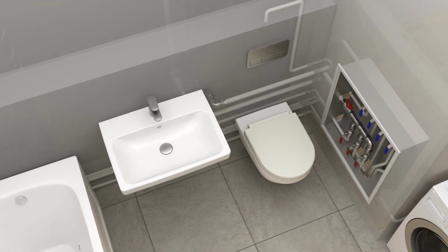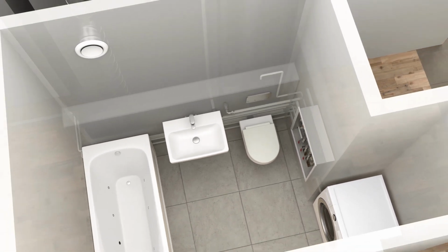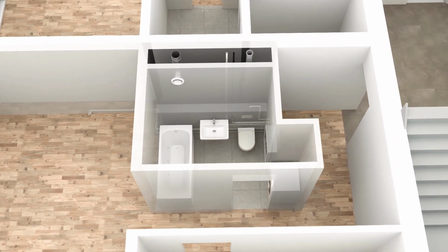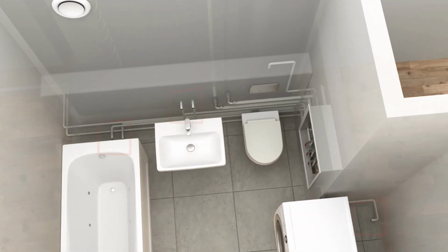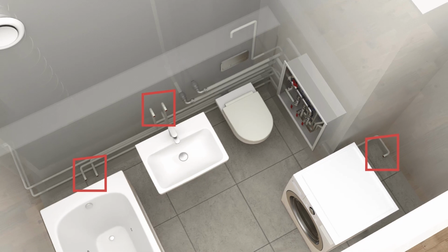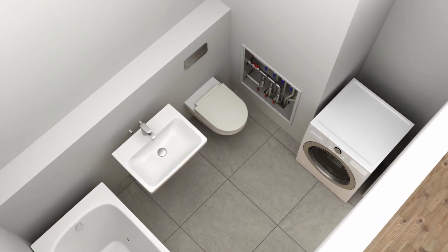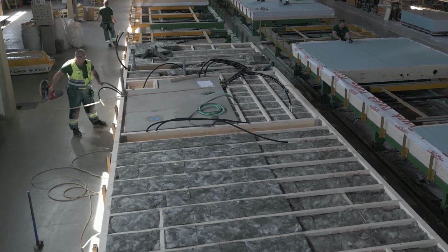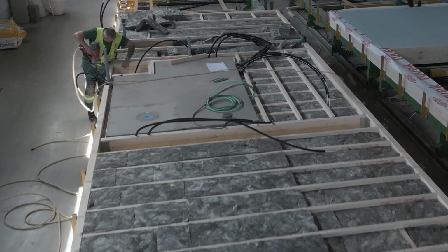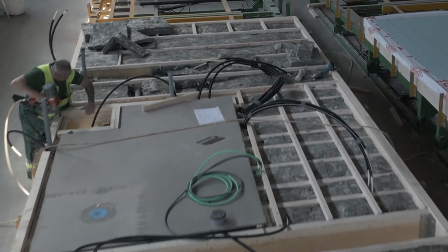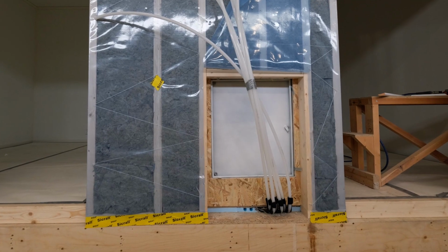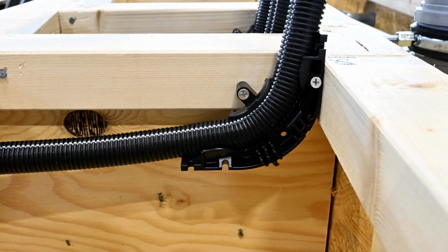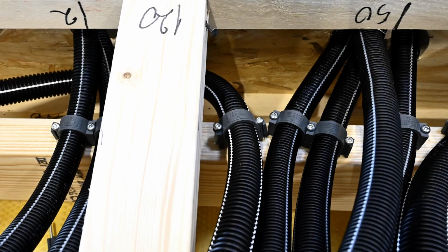The domestic water pipeline is usually located in the area of the wet rooms, kitchen, and in the case of larger dwellings also in a separate toilet room. The pipes are installed in the wall adjacent to the water consumer, such as a toilet bowl, sink, a washing machine, or any other appliance or fixture. For water pipes that are installed in the walls, as a rule, a pipe-in-pipe system is used. This means that the entire water pipe is enclosed with another protective pipe. In order to be able to make changes to water pipes in the future, the protective pipe must be strongly fixed to structural elements, beams and posts.